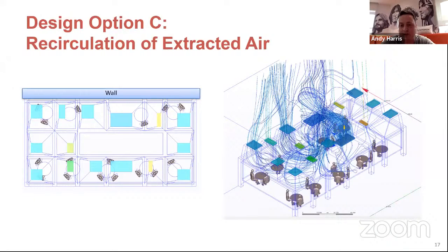That image that you're looking at now on the right is showing that we're getting recirculation on that chimney. One or two of the others showed the same. We did a similar modification to the design to correct that, which we'll show a little bit later on. But this one was the worst one. It was recirculating back down through the opening in the roof. It was feeding itself. It was feeding other outlets, which means it's actually crossing other tables, which is not a good thing. So we had to look carefully about how we could fix that. So we go to the next slide.